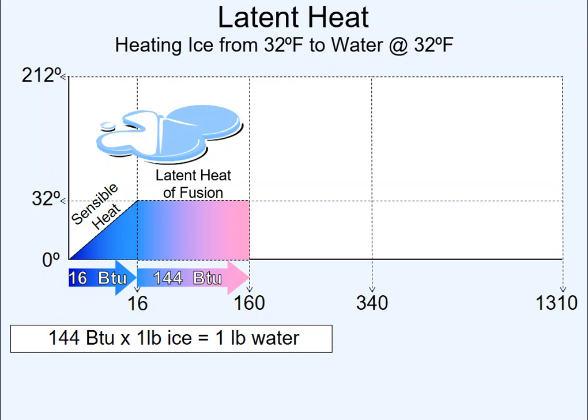So what are we going to have to do? Well, you have to put those coils through some sort of latent change. That's why they're the evaporator and the condenser, because in the evaporator there's evaporation happening, the process of liquid refrigerant becoming vapor. It's kind of like boiling water on your stove.